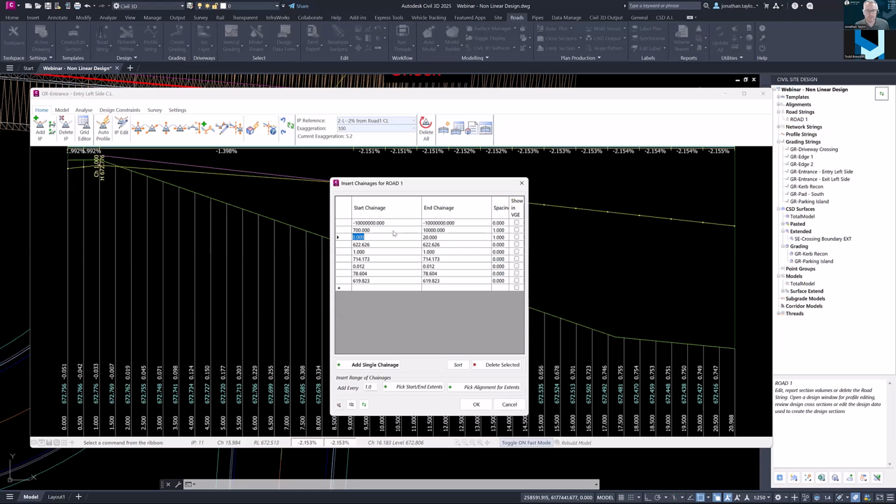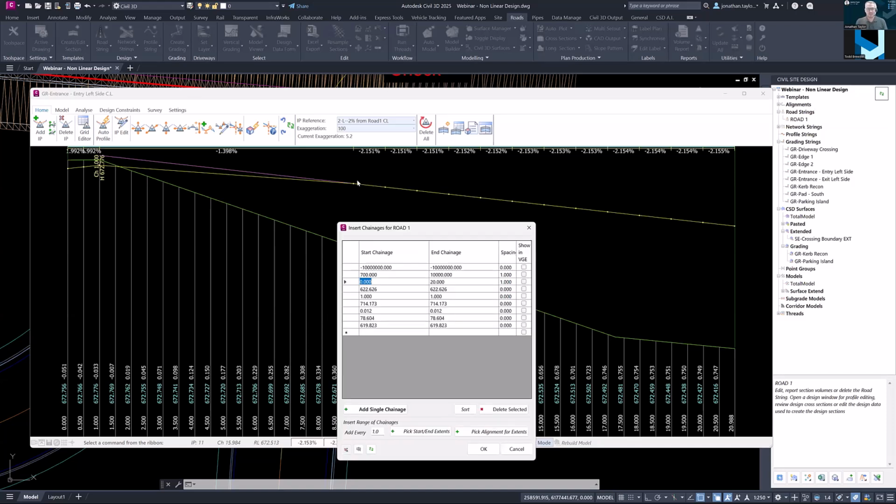I've also done it for the end. So from 700 to the end, extra sampling of 1 meter. That's where the constraint source is, so I want that to be projected every 1 meter. If I left the sampling on the road at every 10 meters, I probably only would have seen that constraint. I'd probably only match on it maybe once or twice. Whereas this way, I've got lots and lots of sample positions to match onto, which is helpful.